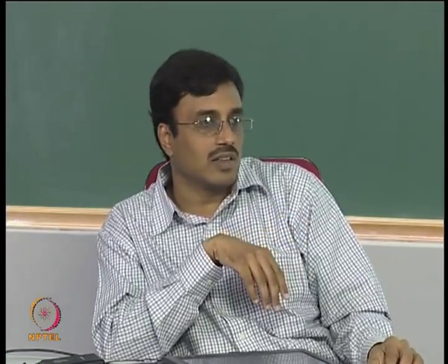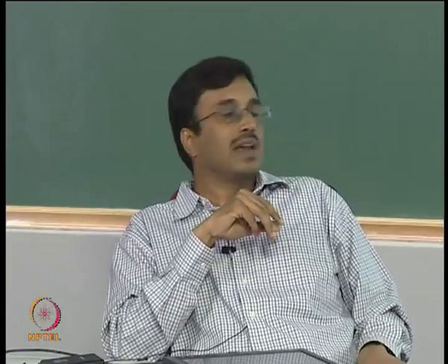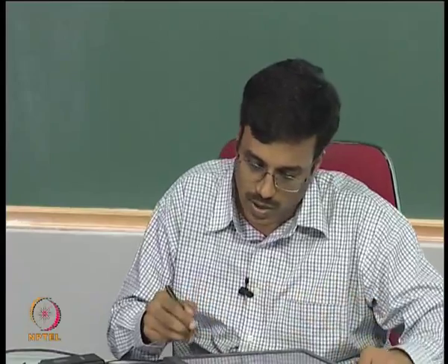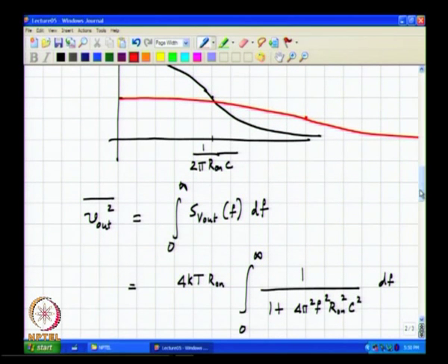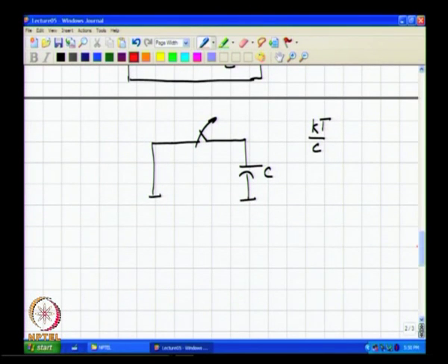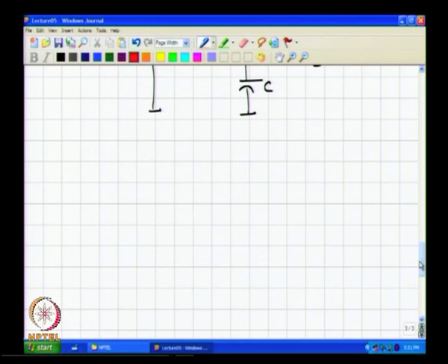While it being an absolute constant is perhaps surprising, you can at least see that these are two opposing effects, and luckily they cancel out, okay, making the mean square value of the noise voltage held on the capacitor independent of the resistance of the switch, and it only depends on the capacitor. Now, what implications does this have on the track and hold design?